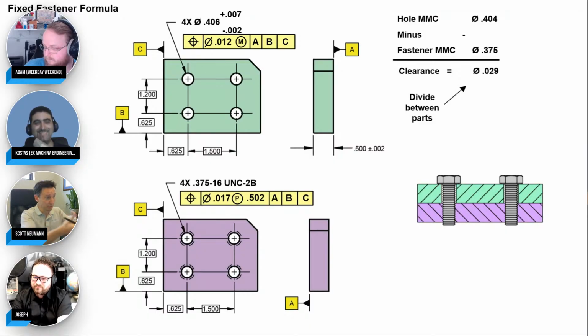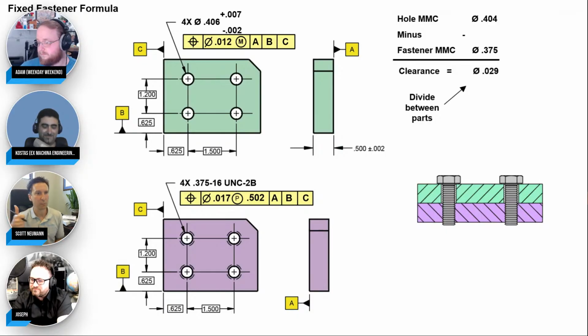So what I'm going to do is put 17 on there. Now, a good quality engineer is going to look at that and say, ooh, I see you want 17 on the pitch, but I want to make a cheap gauge on the minor diameter. So I'm going to artificially guard band the tolerance myself. That's what I recommend quality do. You guard band artificially. So, all right, we're going to use a gauge for this. So we're going to bump it down to 15 thou and go off the minor diameter. And we still think we met your function. Cool. You do your thing.